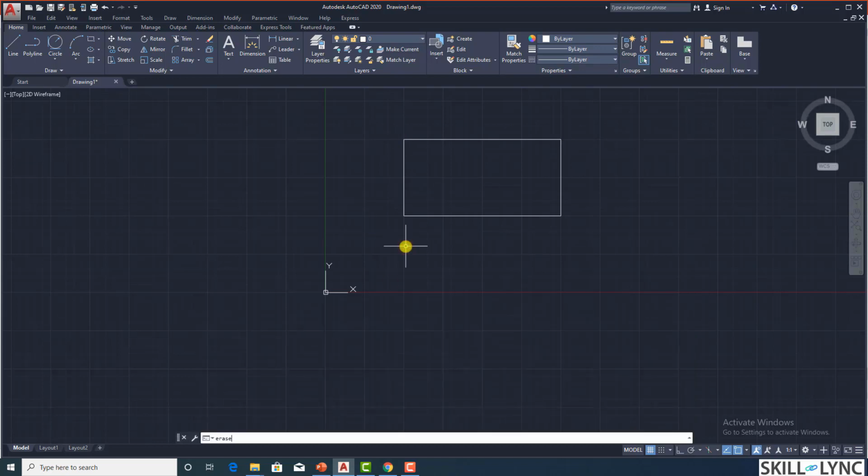Okay, so that's it. Let us use the erase command to erase the sections. You can take note of this: it is not a single object, it's separate lines. That's why when you use the erase command, you have to select each and every line to delete them. Having selected all 4 objects, complete the erase command by clicking on enter or space. Basically enter would work anywhere if you are working in this drawing area, and if you are working in this, then you can click on space to come out of the command.